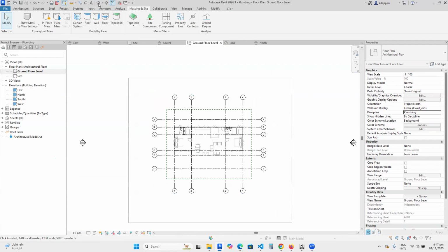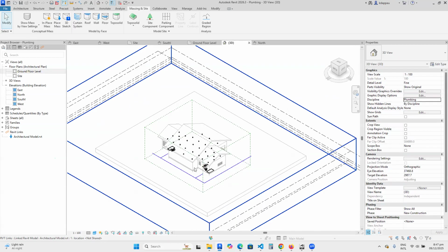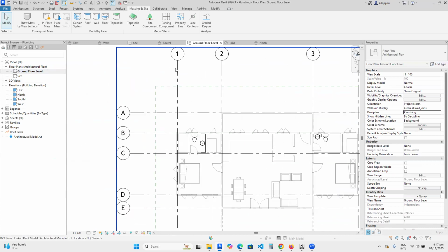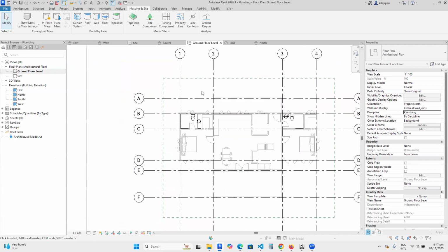You see, this model is three-dimensional as we are looking at it. If you go to a 2D view, the 2D view means that you are looking at the building from one plane, from where you are looking at it, and then you are looking to a certain plane, depending on how far you are looking. So if, for instance, I am on the ground floor here, standing on the plane at grade 1, and I'm looking from this plane, and I want to look all the way out to grade 2, then anything between grade 1 and grade 2, I can see.